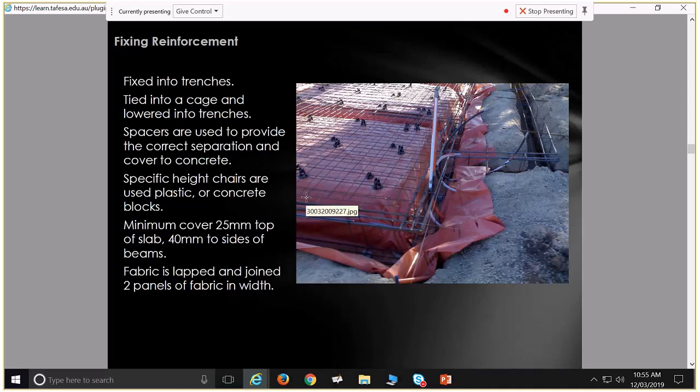So we've pretty much covered all that in our discussion. One thing we didn't cover is concrete coverage. So this steel has to be protected from the atmosphere. We can't just have steel right by the edge, because if it is right by the edge, then it can corrode.